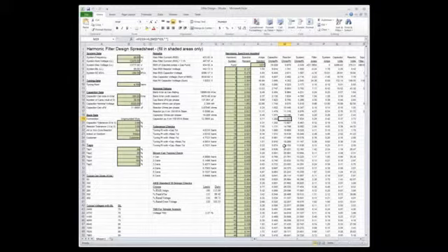So you may right out of the gate say, oh, well, I need X amount of power factor correction. And that's good, but you need to perform simulations and do frequency scans with that design hooked onto the bus to make sure you're not sitting at an integer harmonic for almost all of your normal conditions.